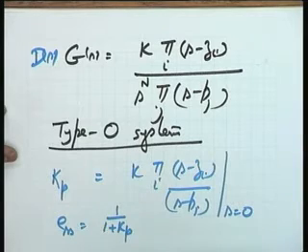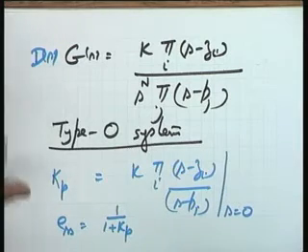kV is 0. So what is steady state error to ramp input? Infinity. Same will be the situation with Ka please. Ka is 0 and the steady state error to acceleration inputs is infinity.